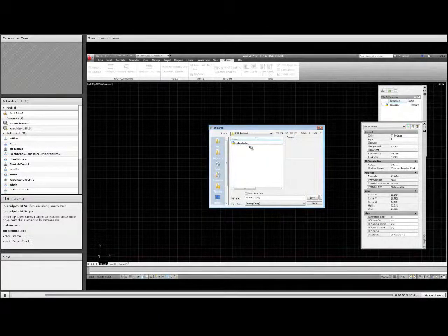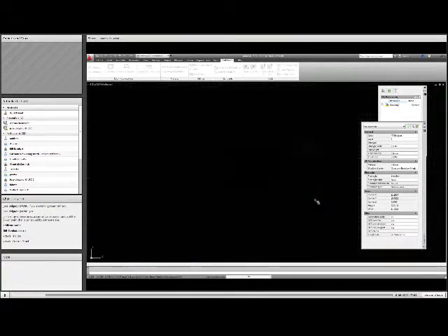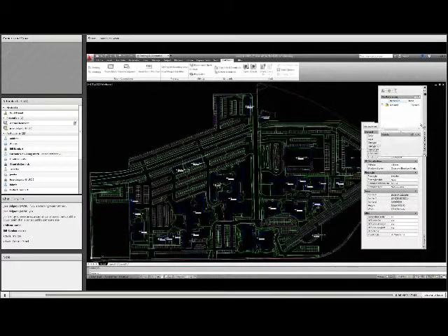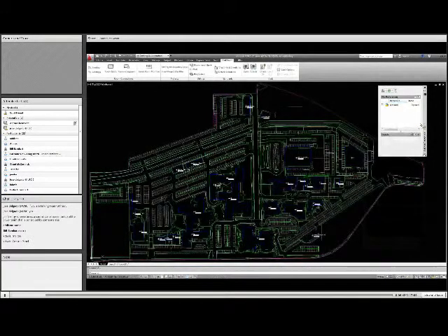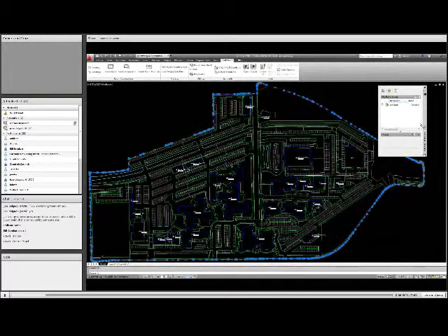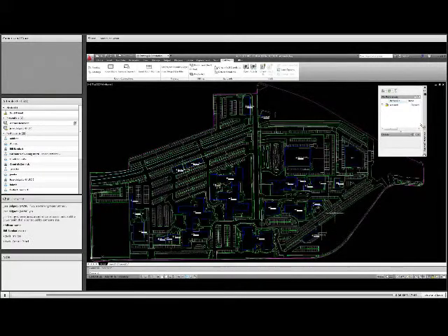This is only a subset of the data. I just wanted to have something to work with. There are some nice clean polygons in here. There are some buildings, some streets, some vegetation areas. With this, we have some custom utilities that we created that allow us to prepare the CAD environment for GIS. And we do that using ArcGIS for AutoCAD, so we're able to create feature classes inside of CAD and all kinds of fun stuff like that.